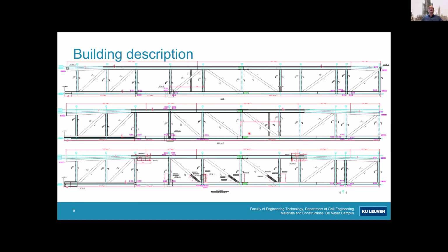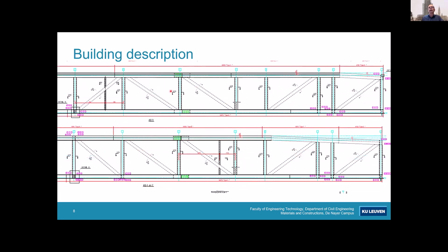Okay, so this is the truss beam. You will not see it on your screen, but I will try to make a magnification of it. Perhaps then it becomes clear. There are some numbers for the vertical studs, and they called it V10, V15, V20, and such on. The V means that it's a vertical stud, and that's nice because in English and Dutch it's the same. And then the 10 is the millimeters, so the thickness of the hollow section. So you have 10 millimeters at the right-hand side.